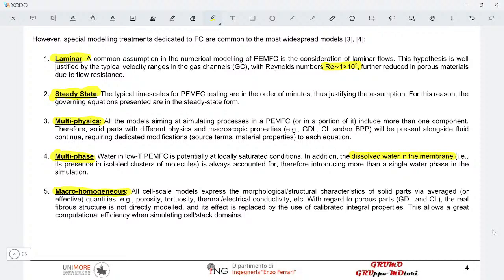So this might be critical, and this is why in the modeling of catalyst layers, we will talk about it next week, there is a class of models which is called agglomerate models. You might be familiar with those, that is trying to put itself in between a purely macro homogeneous modeling and a locally based modeling of electrochemical reactions. Basically, just to conclude on this, you can't imagine to introduce in your model each and every site of platinum molecule for electrochemical reaction.